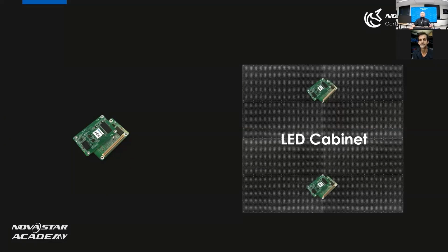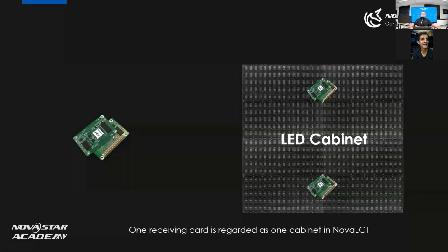This is normal. If the resolution of the cabinet is bigger, more than one receiving card will be installed inside. But here is one tip for you, because when you use our software Nova LCT in the screen connection, there's one thing that we need to do for the screen connection. In the default settings in the software, one receiving card is regarded as one cabinet.